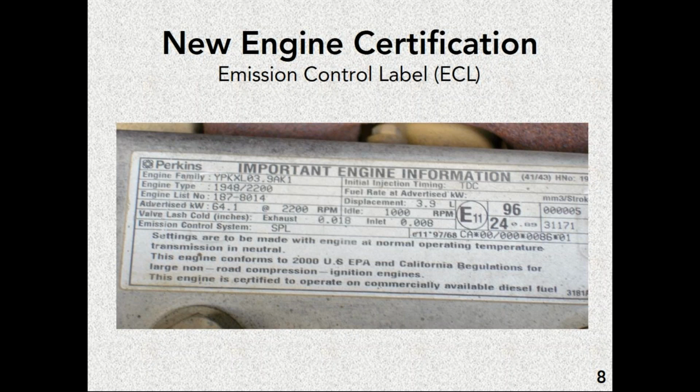In fact, you can see in the language down there, it says this engine conforms to 2000 US EPA and California regulations for large non-road compression ignition engines. So from that phrase alone, let me tell you what you can figure out. First, it's a 2000 model year engine. Second, this is an off-road engine because it says non-road.